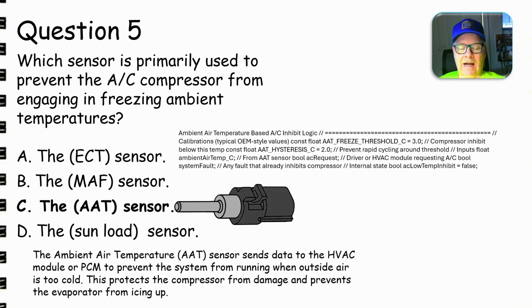That way I could actually watch it, and if I suspected a problem with the fan, I would watch that. That was before I taught myself to spin the fan through and look for open commutators. But I could tell if the engine controller was turning the fan on or not by watching that voltage while the engine warmed up.